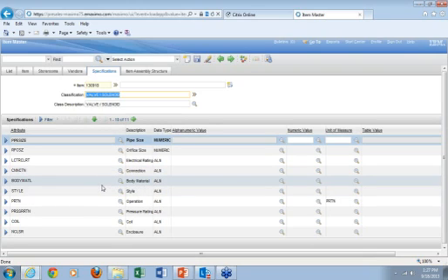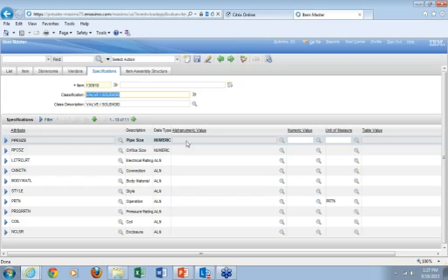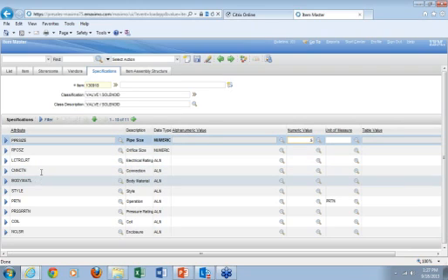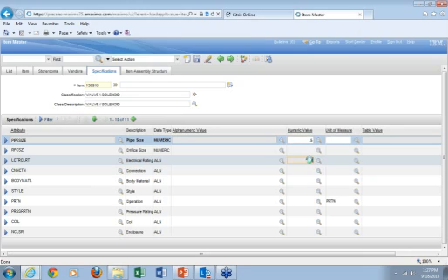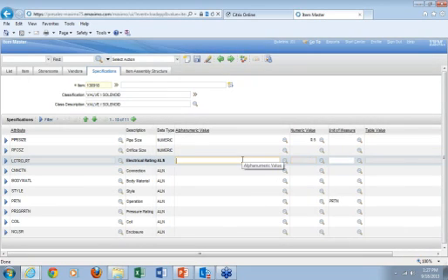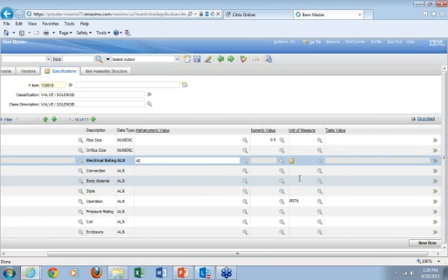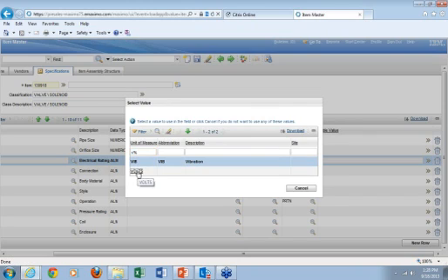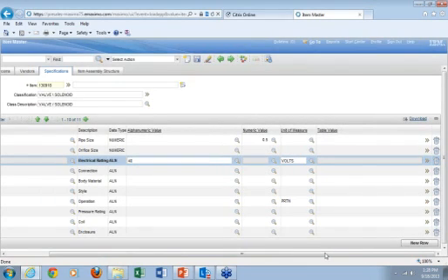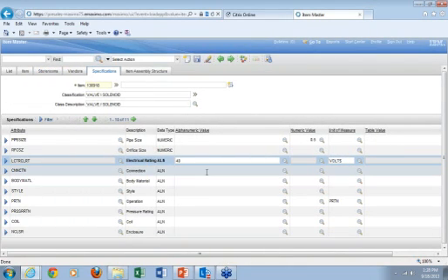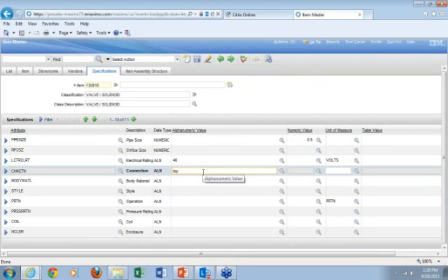Now I'm not going to populate all of these just for the sake of time, but I'll say my pipe size is 0.5. I can say I've got, let's see, an electrical rating of 40, and I'll put in a unit measure, V. That doesn't like my V, so let's pick it here. We want volts. Okay, I have a connection here. Let's just say that's top. Oh, and maybe body materials, brass.